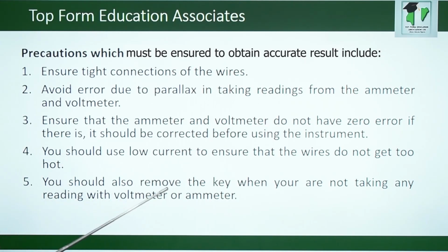You should also remove the key when you are not taking any reading with the voltmeter or ammeter. Otherwise, it will run the battery or the cell down. So you must remove your key when you are not taking any reading with the voltmeter or ammeter.